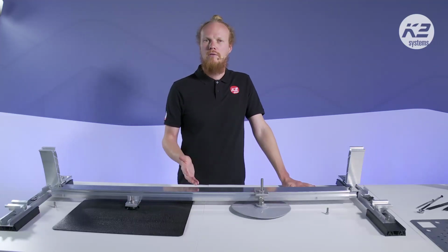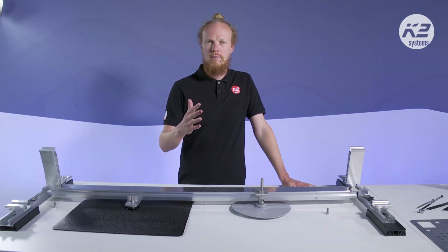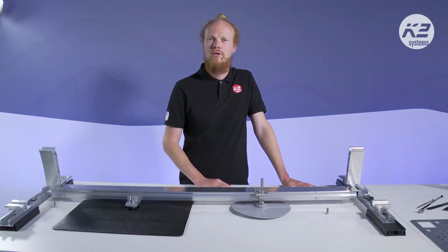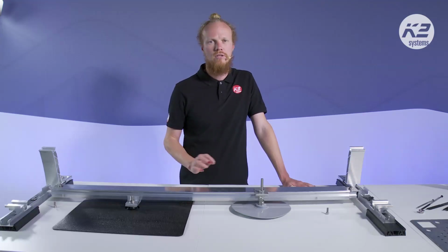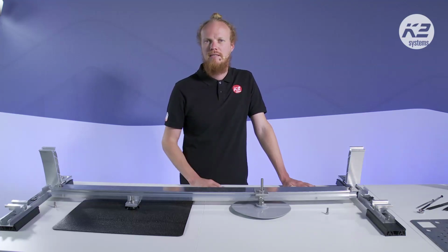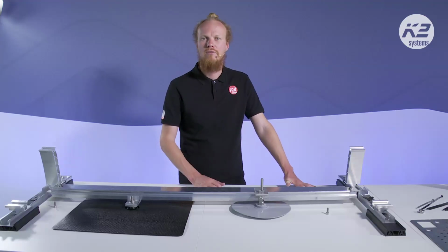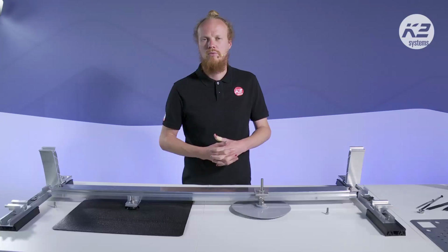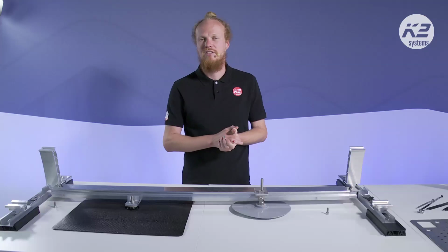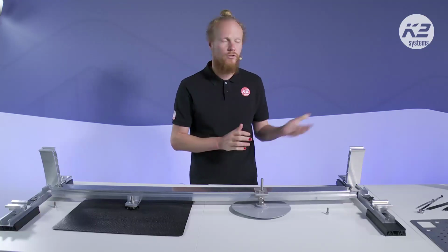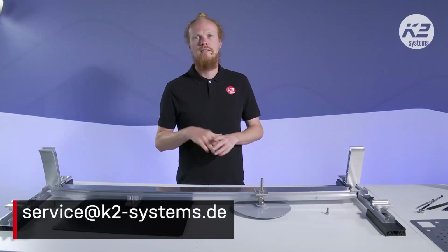With pitched roofs, though, the inclination is a little bit higher and the roof structure is very different. So you are limited in many cases as to where and how you can put the modules. While practically it is possible to put modules at an inclination for a higher roof pitch, it's often not so practical from a construction point of view. If you have any questions or situations where you would like to do that, you can send us an email. Our technical sales team, which we're part of, is on the screen now: service at k2-systems.de. We'll be happy to take a look at it.